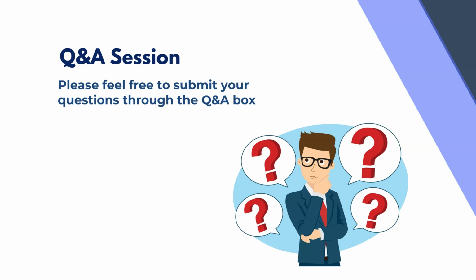The alarm philosophy that you have already set in stone at the start of your plant management tells you, coming towards these types of alarms, how to manage them. So with your alarm philosophy here, rationalize, make sense of it. Is it necessary? Is it an unnecessary alarm? Is it just a nuisance alarm? Can we deprioritize it? Things like this are what it means to rationalize your alarm systems.